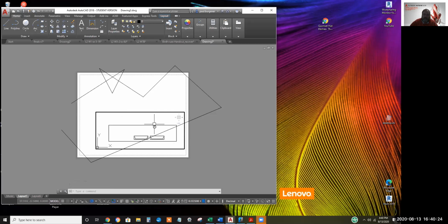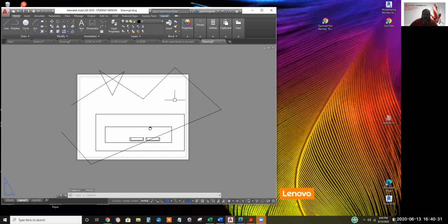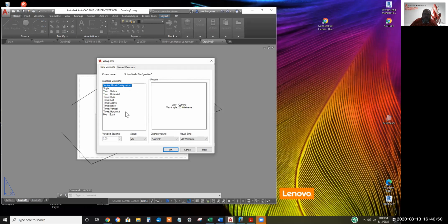Anyway, getting back to the exercise, let's say there's the floor plan of our mobile home. I'll double click and I'll make a second viewport that shows a close-up of the sink right here. I typically copy the viewport, but you can make another one. I think vport is the type in. Or mview is another type in. Anyway, you can make a single viewport this way.